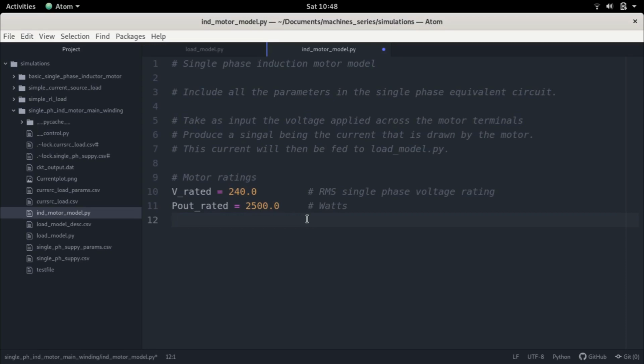Now the input power can be found out in various ways, and that is mostly through the efficiency. So we need to know the efficiency of the induction motor at the maximum power rating. Okay. Now this usually can be found in a manufacturer documentation where they perform several tests on the induction motor and they provide several efficiency curves, right? So usually you will find an efficiency curve which is the efficiency versus the output power. And usually any motor is designed such that it will be most efficient near the maximum rated power, right?